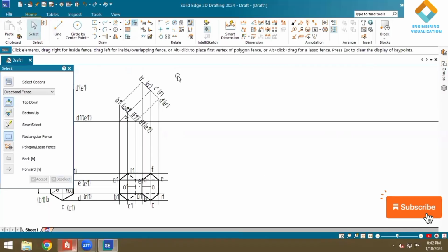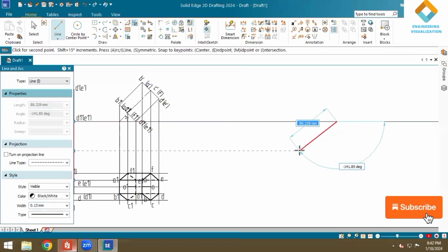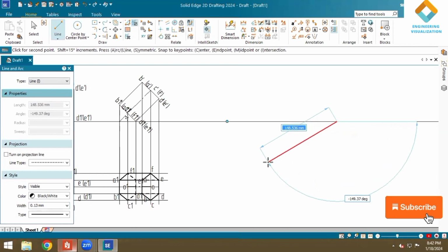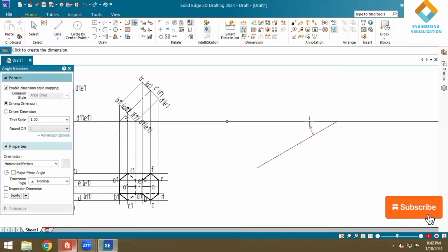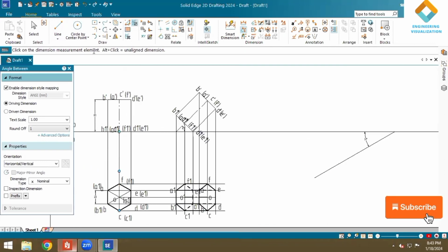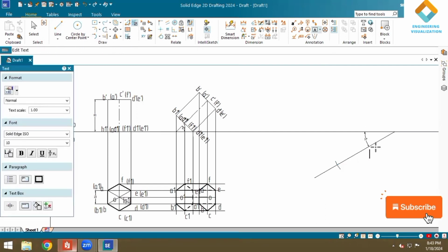So see the question paper. Angle of inclination to VP, it is 30 degrees with respect to the axis for the VP plane. So the angle, and I'm drawing here. So here the first arc length we should be drawing at 60 mm. Okay, need to find out the beta angle, right? So first position front view, it is 60 mm. So draw an arc for a length of 60 mm, by taking one reference point, you can give this as O1.